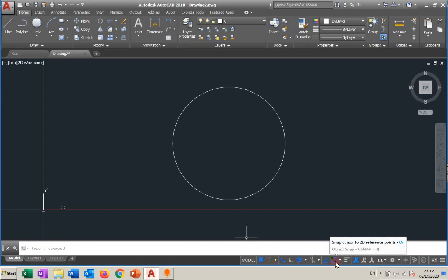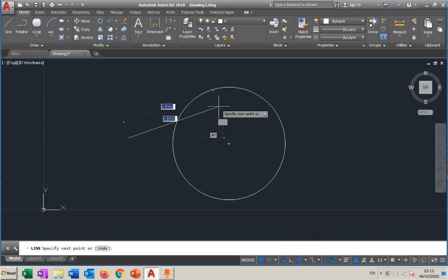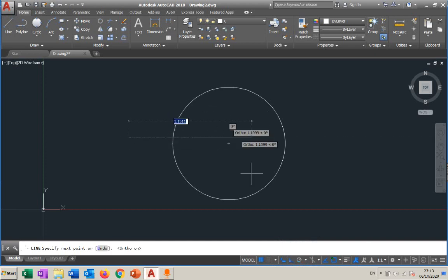So I will refer to them by these names, like object snap. I'll tell you, in object snap, please activate something, or in object snap tracking, make it off. For example, ISO draft, make it on or off. Anything that we refer to by name, we call turning off and on in the status bar. You will come here and do these things. We'll show it to you, but you have to know that this is important while drawing. You always look here, and sometimes you turn something off or on. For example, while I'm drawing, you may see that something is turned on and off there. Look, I turn on this one, turn off the other one, and by pressing something I turn it off again.